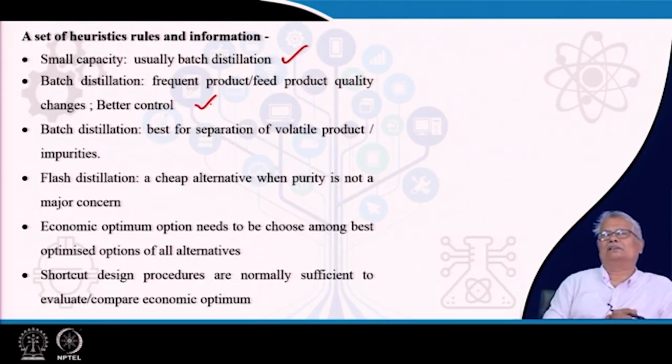You will also look at another case where batch distillation is important. Very often you will find there are streams which are contaminated with either a high boiling or a volatile product. Say a heavy oil is mixed with gasoline. The boiling point difference is substantial. The quantity of gasoline is small. So, in such cases, possibly what you will do is simply use a batch distillation, which you will